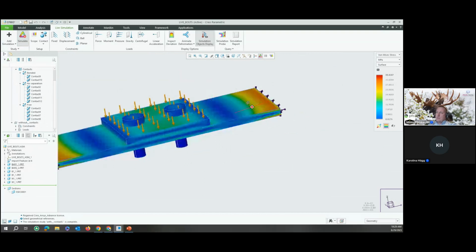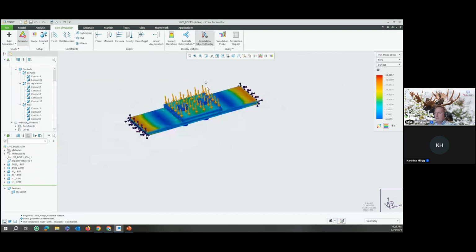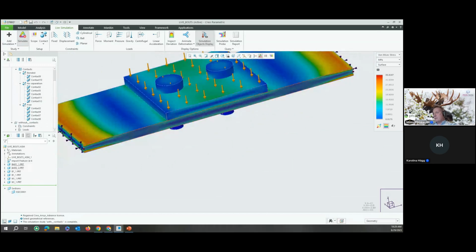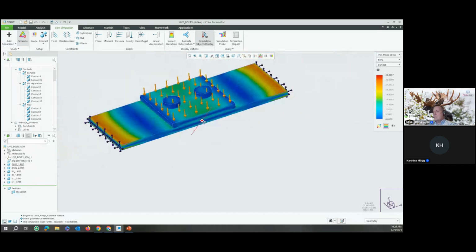And as you can now see, the stress distribution is quite different. Now this plate is also having a maximum stress on bottom and on top of the structure, and same thing in here. The previous stress concentration here is basically gone. And this is just because we have a bit different contact model in the system that allows the relative movement between the pieces, and thus making you able to find out that, okay, this is maybe a bit better description of how the system is behaving.